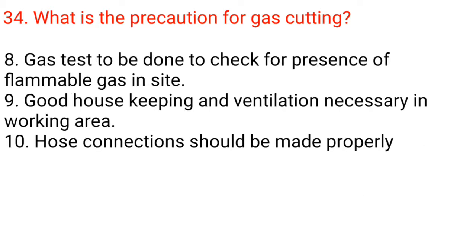8. Gas test to be done to check for presence of flammable gas in sight. 9. Good housekeeping and ventilation necessary in working area. 10. Hose connections should be made properly.